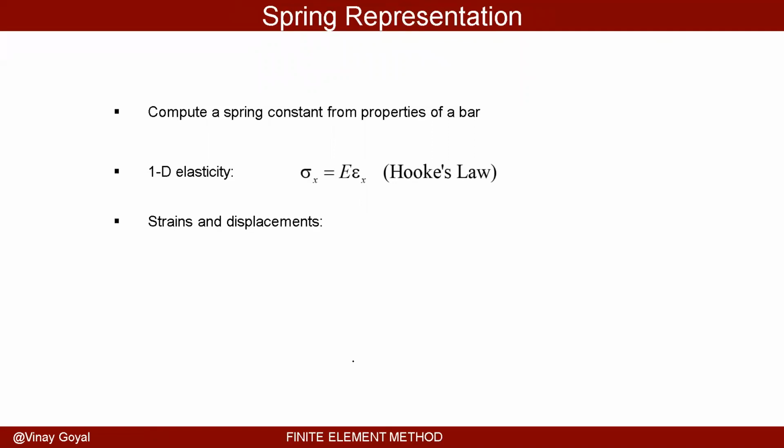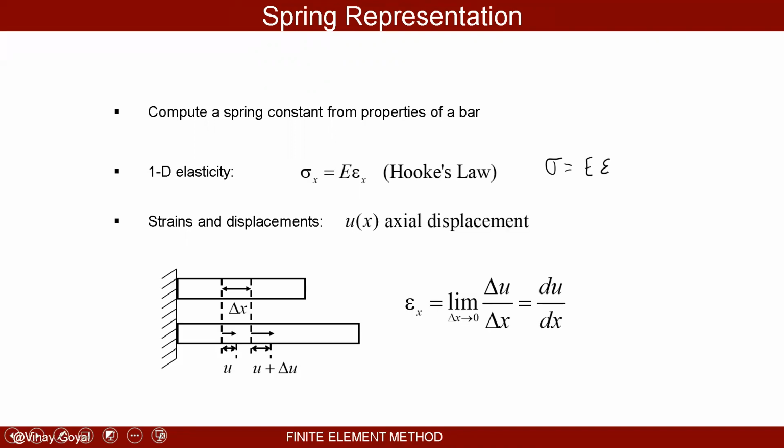The elasticity equations are that stress equals E, the Young's modulus, times the strain. Strain in terms of deflection, we all know that strain equals du/dx. And you can derive that very simply by looking at the change in length. So what is the relative deflection that I have when this point moves to this point and this point moves to this point? Well, that's this minus that, which I get that, and that's divided by the original length, which is delta x. So change in length divided by original length, and that in the limit gives me du/dx.